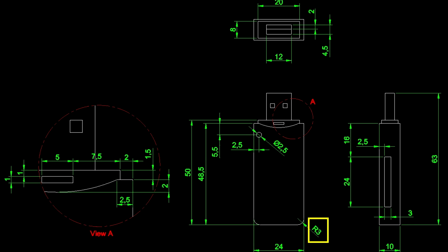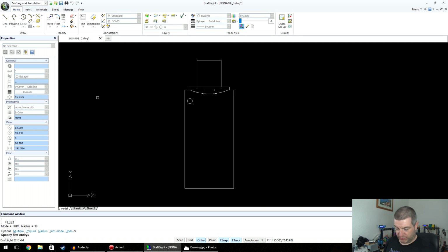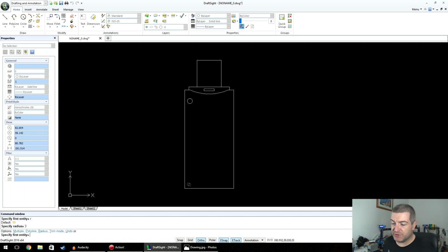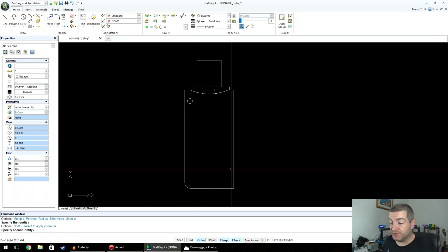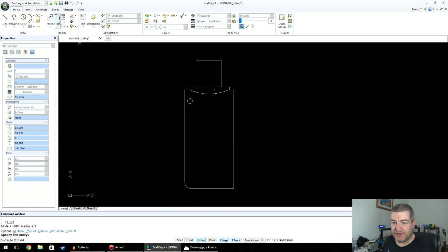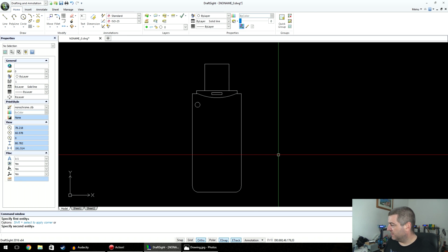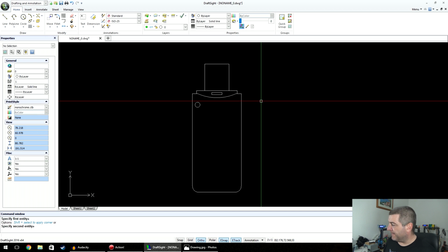Alright, there's a couple of fillets at the bottom, so we'll do fillet. We'll do radius, because we've got to do radius first. And we'll do 3, and then we'll do that line. I'm looking over the top of the mic. And then we'll do fillet again, and it'll remember 3, and we'll do that to there. Right. And I think, apart from the 2 little squares, which have no dimensions on because USB, I think that's it done.